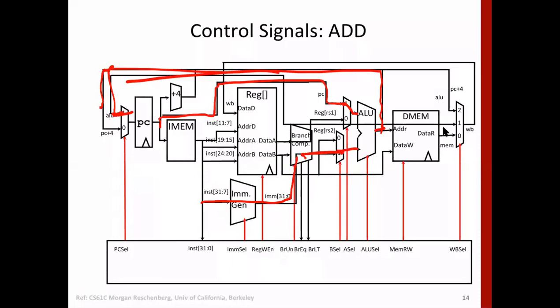In case of all branch instructions, PC select will be 1 for all branch and jump instructions, which corresponds to the upper input. You can define what is 0 and 1, but basically the value coming from the ALU will be selected. But if branching is not taking place, we'll have to increment by 4, right? In that case, how will we do that, because we are always keeping this as the upper one?